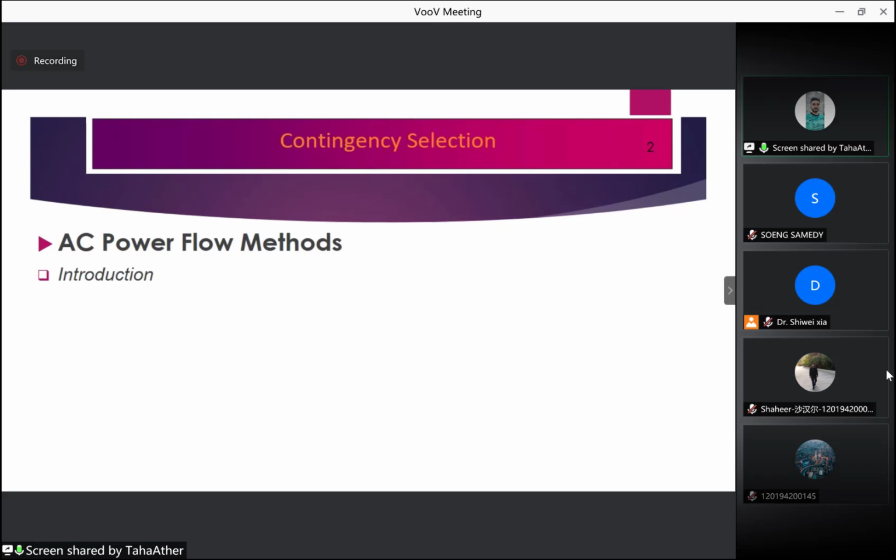When such situations present themselves, the network sensitivity method may not be able to fulfill our required tasks. Although it is a great method, it still lags in some areas. And the operation control system will have to incorporate a full AC power flow for the analysis of contingency. When an AC power flow is to be used to study each contingency case, the speed of solution and the number of cases to be studied are critical. If the contingency alarms come too late for the operator to act, they are worthless.